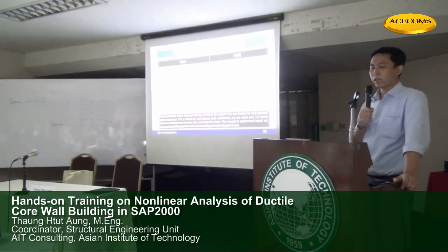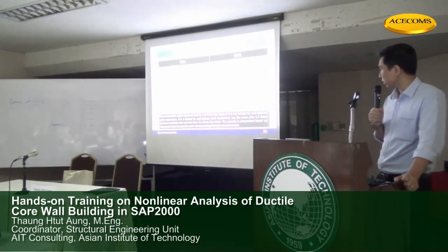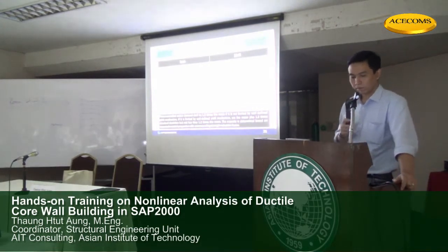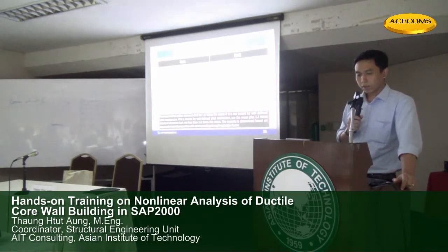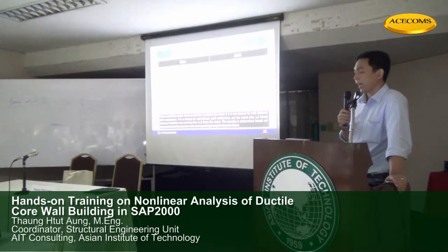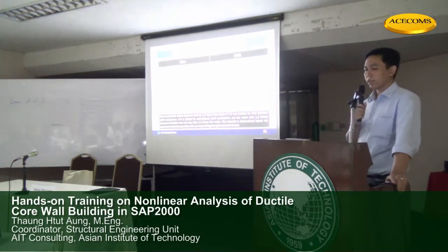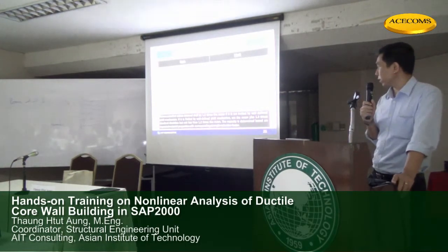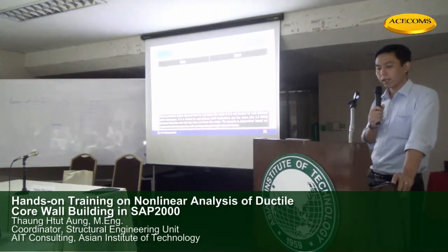This is the shear wall and frame interacting together. Because of the lateral load, the shear wall is behaving like a cantilever column, but the frame is behaving with a shear deformation pattern. So at the base of the building, the shear wall is not rotating too much. The frame is swaying too much, so the shear wall attracts more.